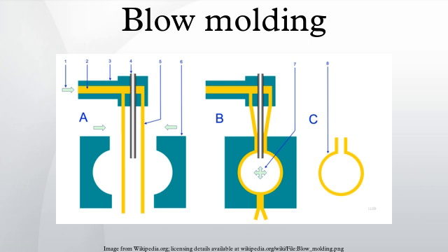Types of EBM equipment may be categorized as follows: continuous extrusion equipment, rotary wheel blow molding systems, shuttle machinery, intermittent extrusion machinery, reciprocating screw machinery, accumulator head machinery. Examples of parts made by the EBM process include most polyethylene hollow products, milk bottles, shampoo bottles, automotive ducting, watering cans, and hollow industrial parts such as drums.